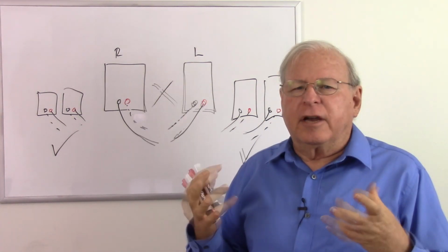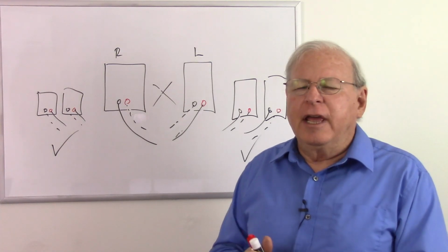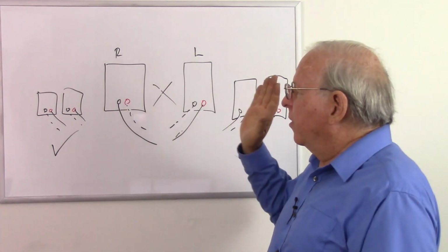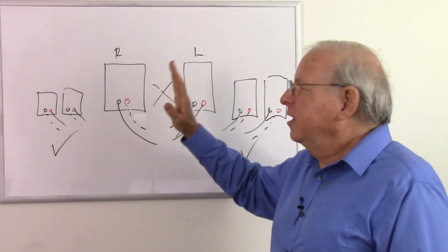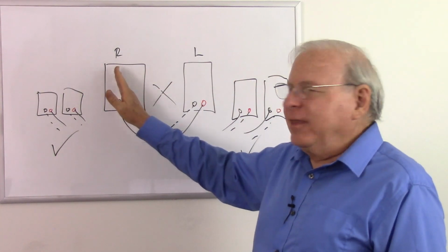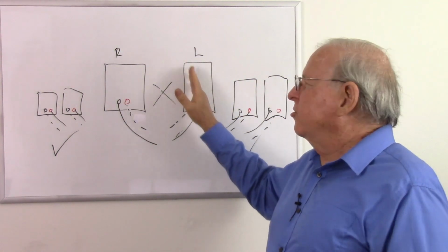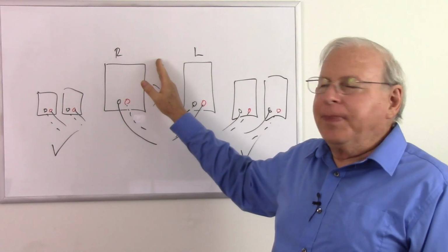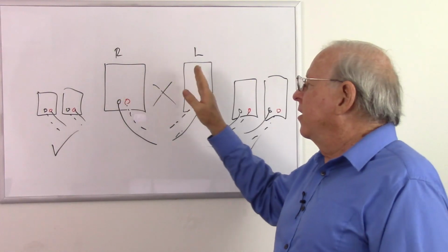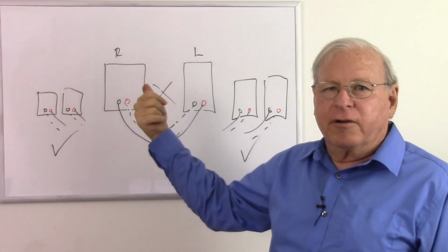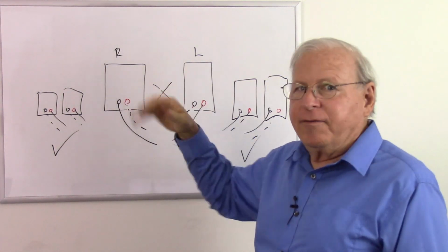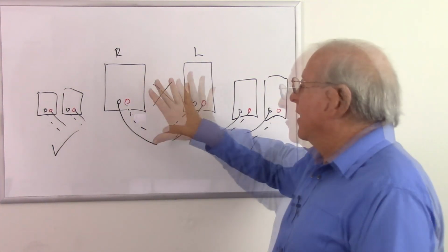You can also get test sounds to test your phasing, and it will be basically white noise. They'll put white noise in one speaker, white noise in the other speaker, then put it in both speakers. You should hear it in this speaker, then in this speaker, then dead between the speakers. If you hear it in this speaker, then in this speaker, then it kind of comes from everywhere behind the speakers, your phasing is flipped. So if you can get some white noise in there, that's a good way to test it.